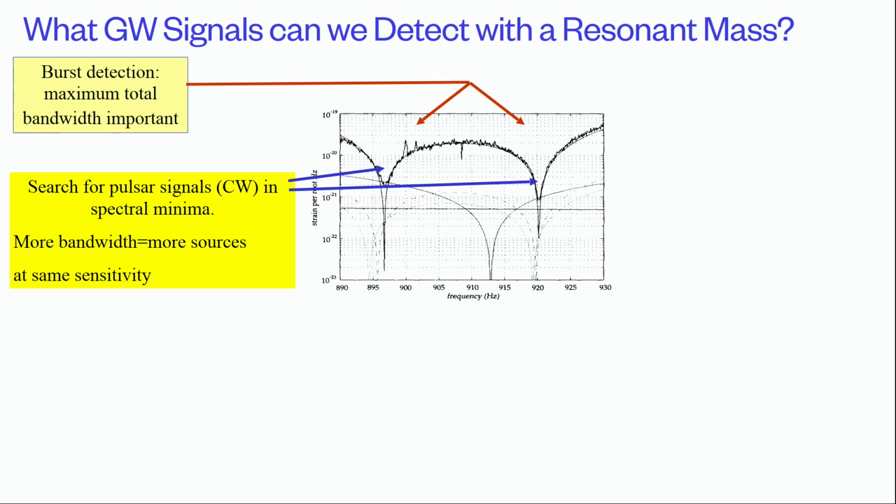Now I'm confused, right? Because I can either think it is per unit of time, and then I integrate for 1 second, or I can think it is per unit of frequency bandwidth. I'm just saying that's a fluke. It's not the same. You don't have to have that way of thinking, but you can. It's only because the unit of hertz is an inverse second that that's true. If a hertz was inverse 2 seconds, then it'd be 2 seconds. Anyway, to reproduce this noise plot, you need to wait for some time. You can't just have it instantaneous there. So you need to acquire for 1 second to be able to reproduce the data.